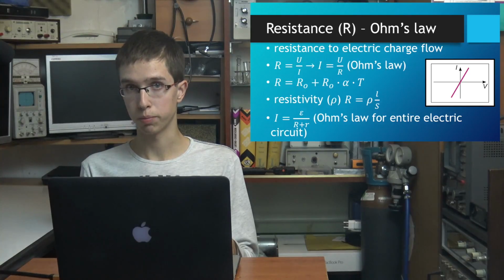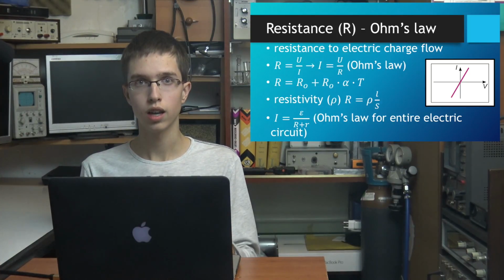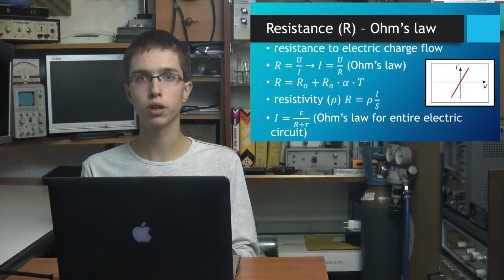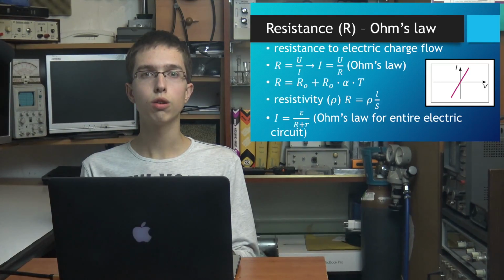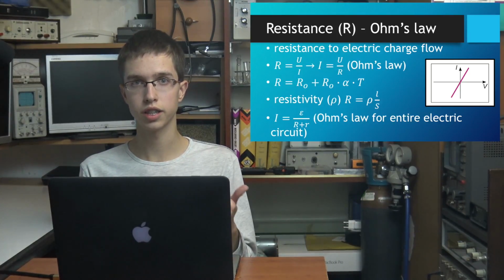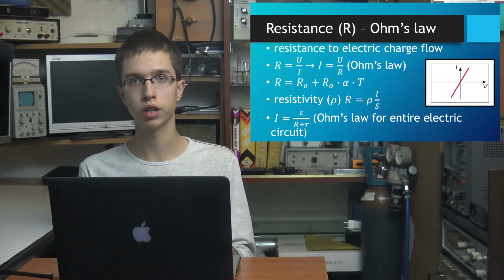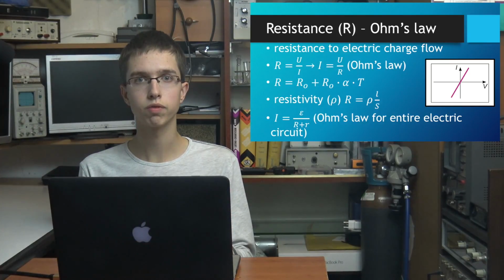Exceptions are very low temperatures, when metal resistance almost disappears, as well as magnetic flux, which we are going to talk more about, expulses, more precisely when metal is cooled down to temperatures below its characteristic critical temperature, which is a phenomenon called superconductivity. There is also a quantity called resistivity, marked with a letter ρ, which is also a property of a matter and is used in the formula for expressing resistance using resistivity, length L, and cross-section area S of a chosen part of the conductor's volume. And here is the formula.